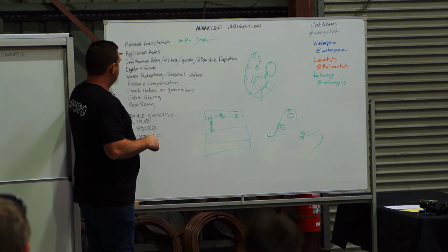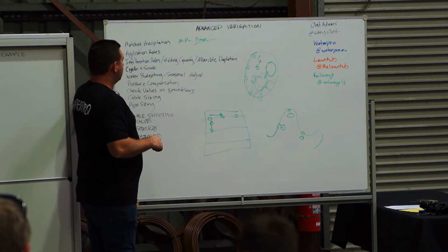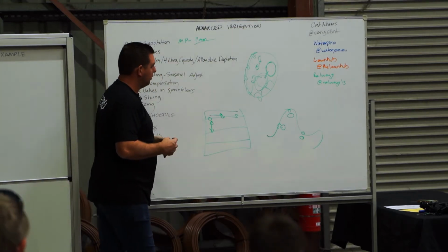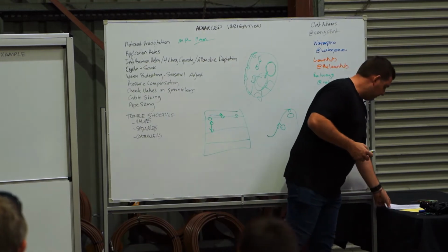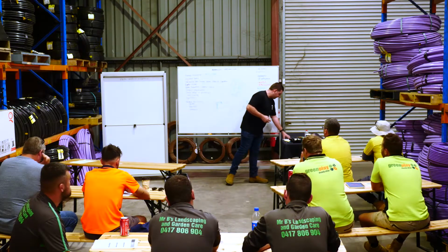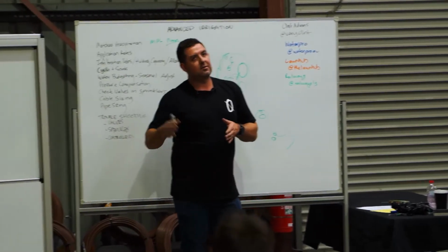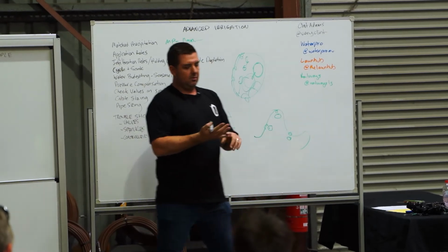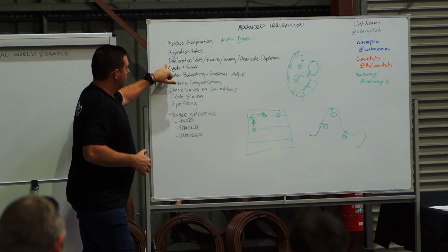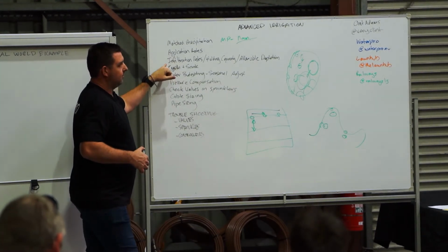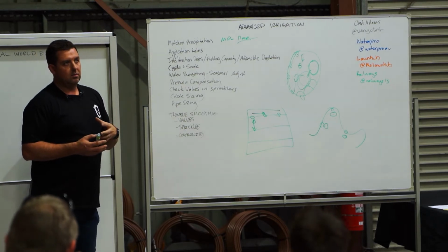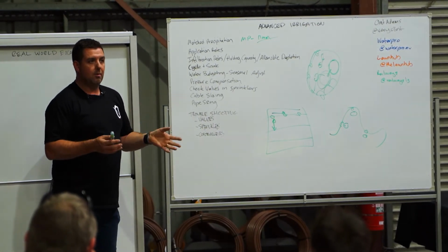I'll try and give you a general idea of application rates. Each product has its own application rate. We've talked about that before, with the MP rotator being 11, the RVAM being 14 and that kind of thing. When we move into infiltration rates, not all soils are the same, obviously, and some soils can handle more water per minute than others.